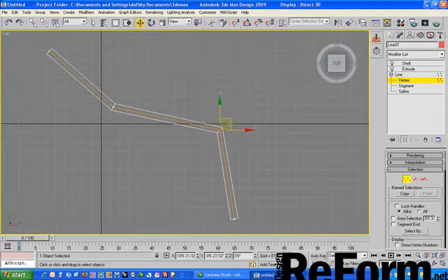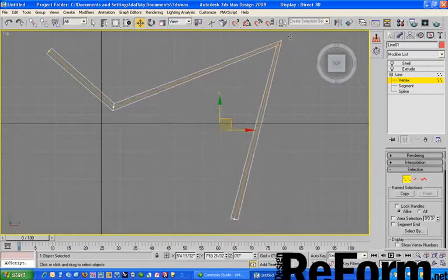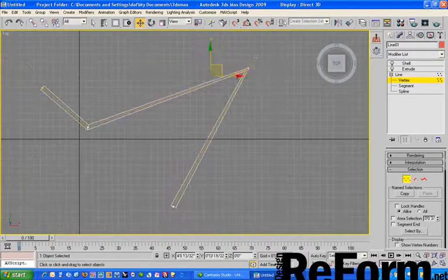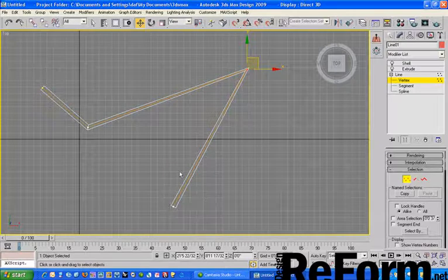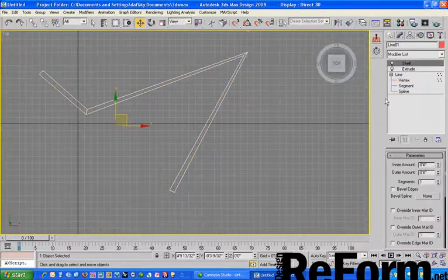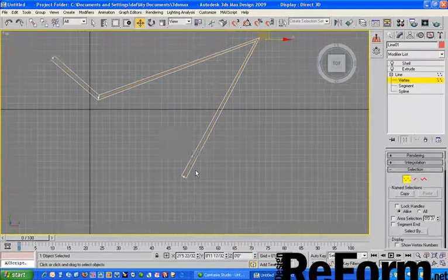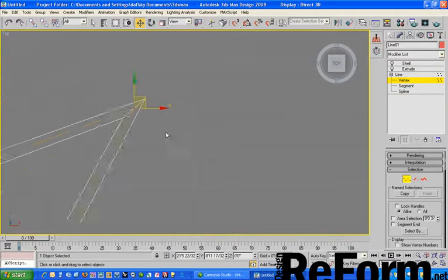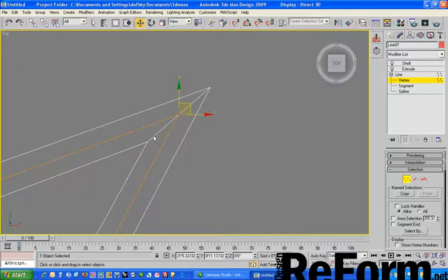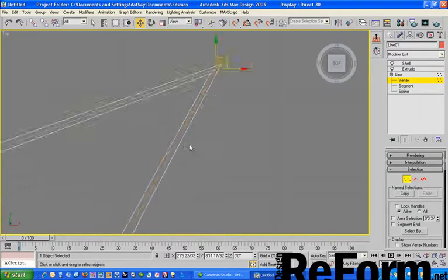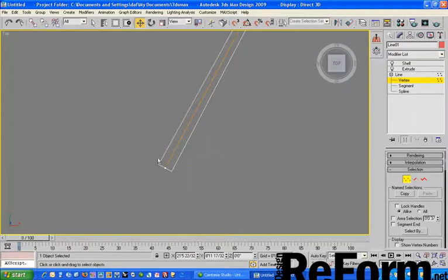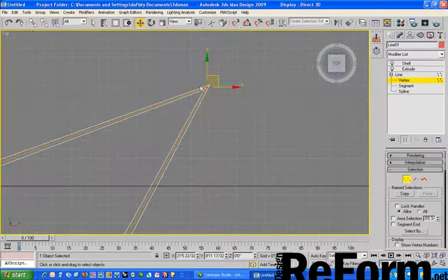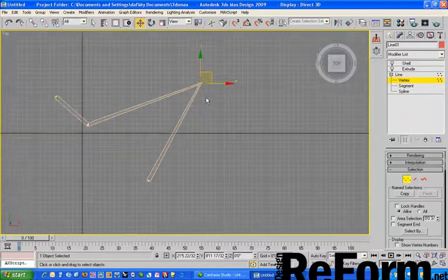But one of the things that I quickly go over immediately on the shell modifier is understanding this tapering effect that we're getting. Because actually, let's go back to segment level. What it's doing is it's projecting whatever amount you put in the shell from perpendicular to the line from the vertex. So at this condition, since we did 4 inches and 4 inches, we're getting 4 inches here and 4 inches here. But that's very different than having 4 inches here, which is essentially 90 degrees from the line, where here it's as a result from whatever the angle difference is between these two lines.